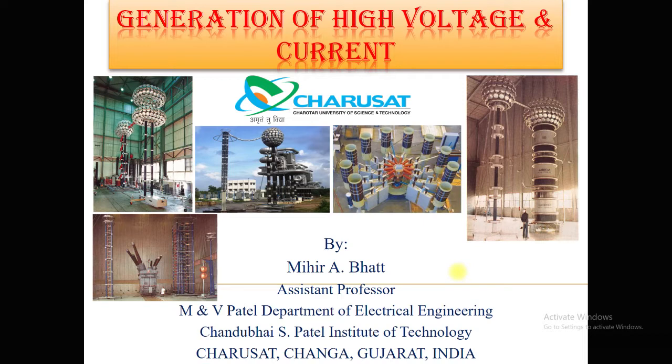Another requirement of using these Tesla transformers or doubly tuned resonant transformer is to study the spark phenomena. We all know that when the potential surrounding the conductor exceeds the corona inception level, there will be ionization of the air, and as a result there will be the formation of a spark.